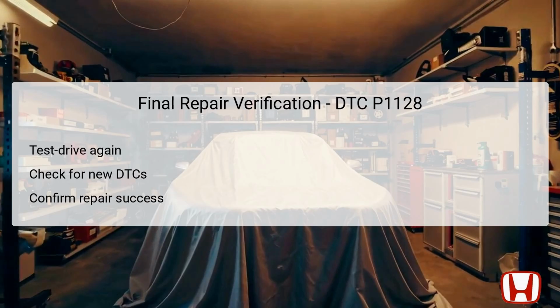After completing all previous troubleshooting steps, an important final verification is necessary to confirm the success of the repairs. Undertake another test drive under the previously specified conditions, ensuring that all parameters are met. Following this, check for any pending or confirmed DTCs using HDS.